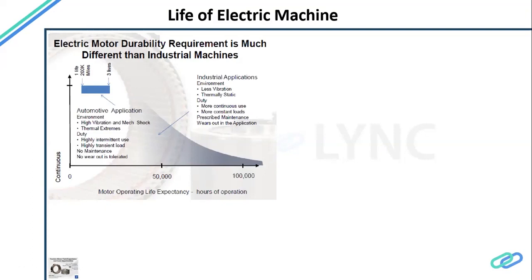So it gives us a different specification for the material to be considered when we consider the electric steel, for example. At high speed, like 12,000 rpm, 15,000 rpm, 18,000 rpm, those rotor laminations, because we have narrow bridges there, all have to hold those windings or magnets.